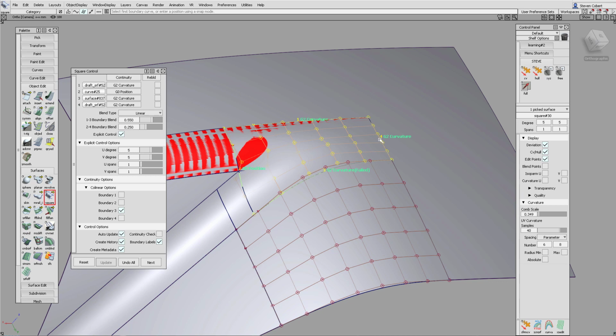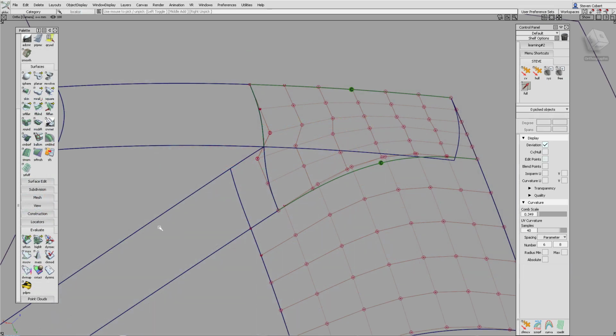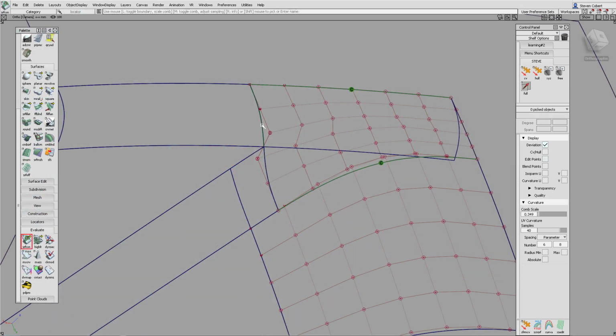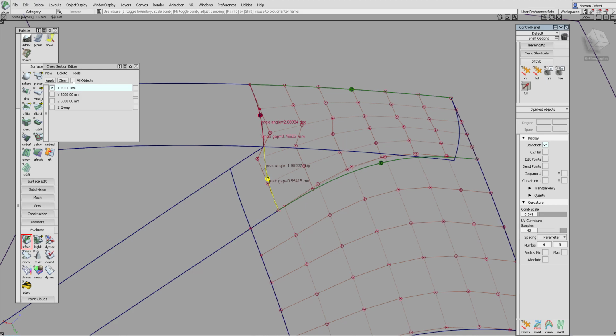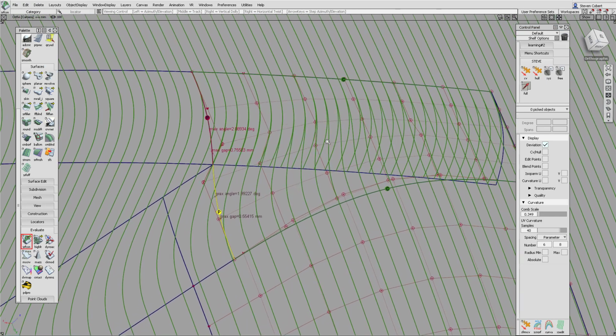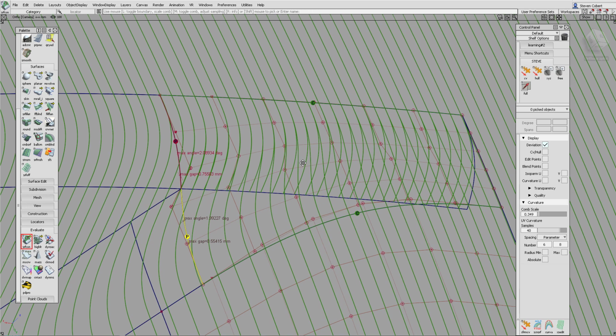You can see that the top fillet is poking through a little. We need to adjust our surface to get a reasonable approximation here. We also need to look at the tangency to the fillets. We're never going to get alignment, of course, with one surface. That's only going to happen once we split the surfaces up. We can use sections, X or Z, to give us a better idea of how close we are to the long fillet. It's only near the top edge that, of course, it's going to be close to this fillet.